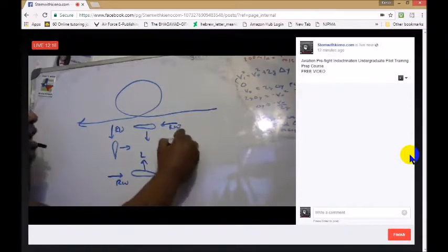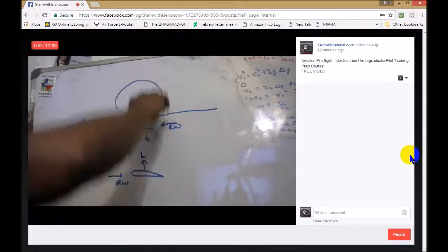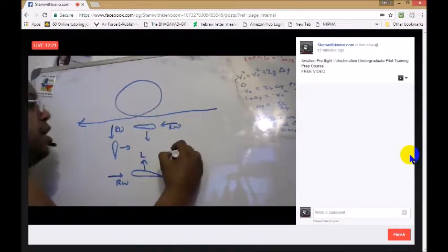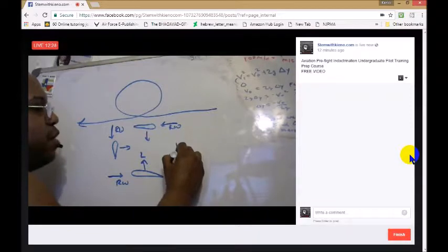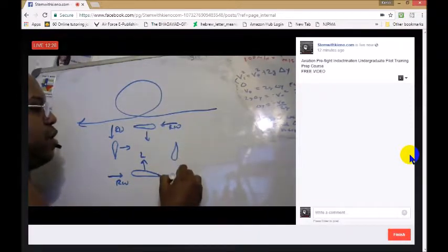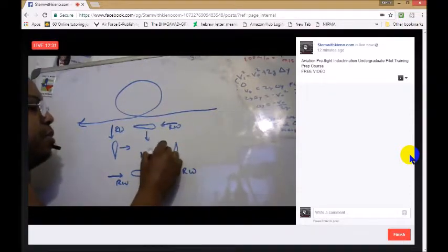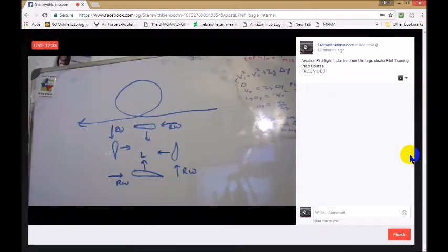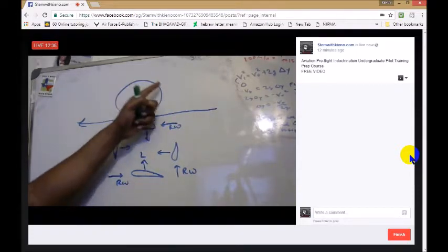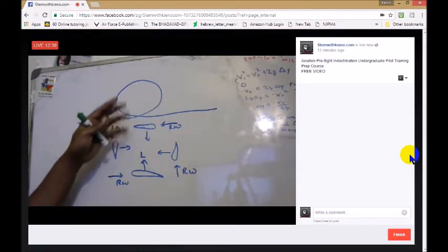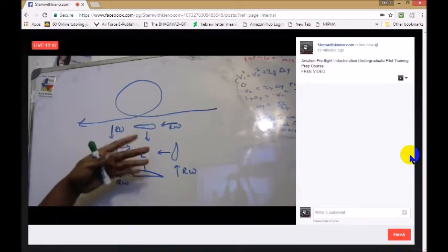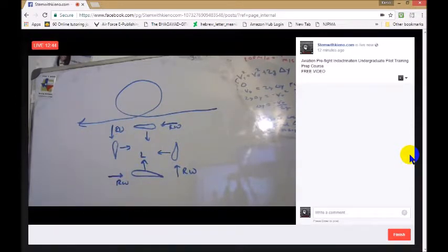direction, and then as we come down into this part of the loop, and we're in a dive basically, the airfoil will look like this. Relative wind will be approaching the wing that way, and lift will be produced in that direction. So in this loop maneuver, basically the angle of attack will be changing, the relative wind will be changing, and you need to be cognizant of that situation and the vectors.